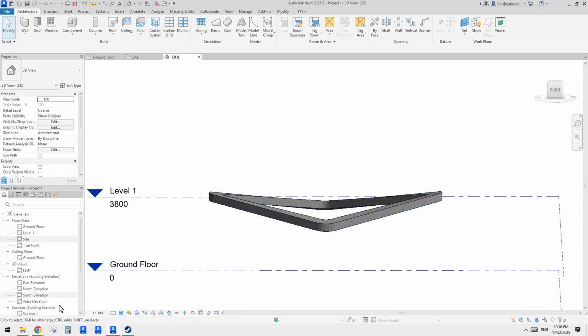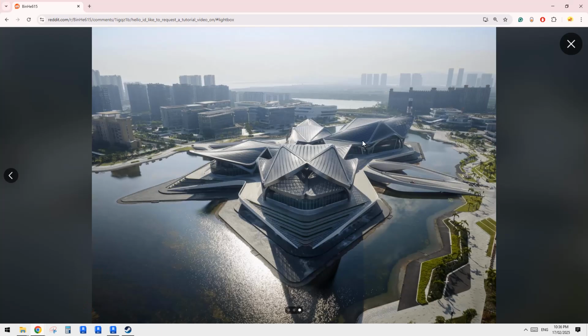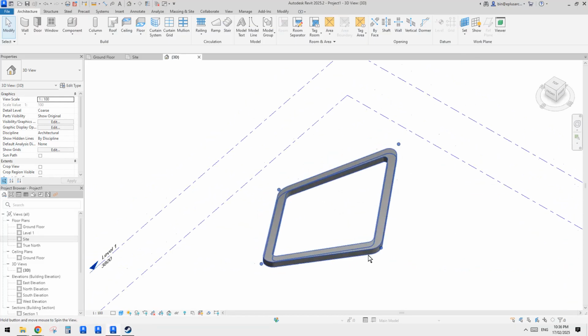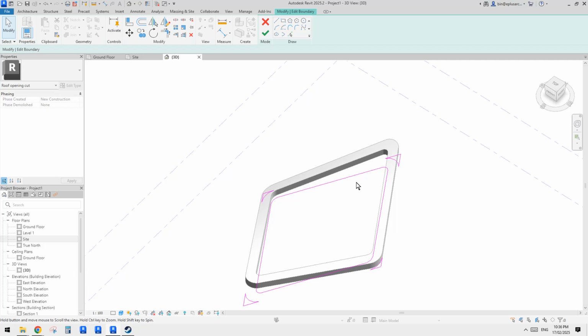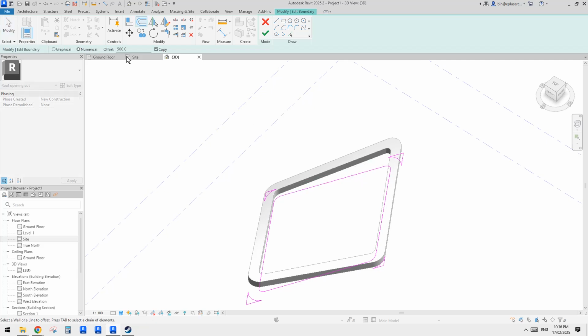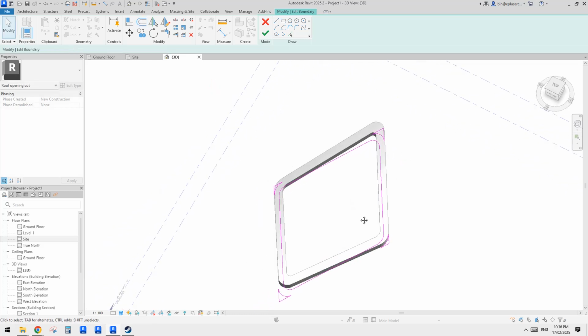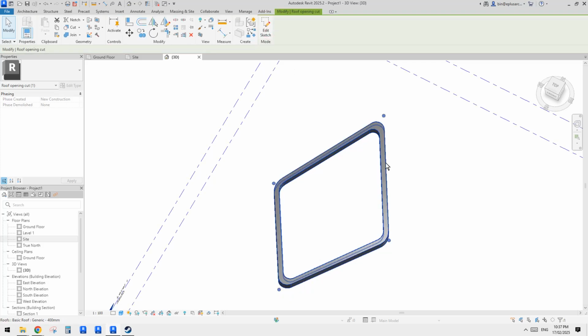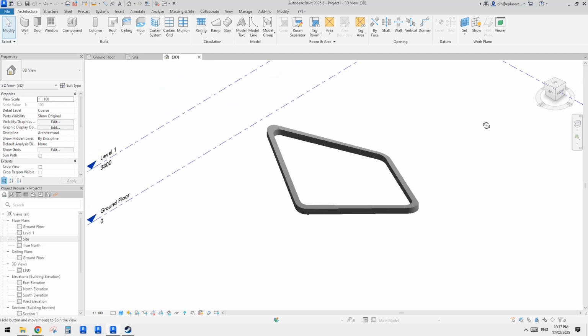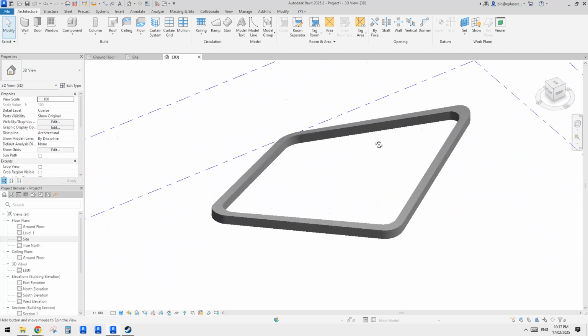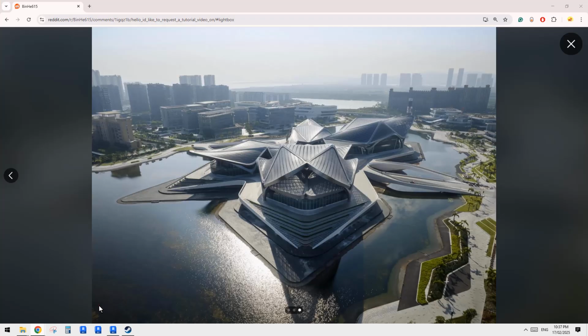Okay, and then quite similar to something we have here. And if you need to adjust the size, for example, we can use offset. So try offset. Maybe I'll just put in 200. Untick the copy and the tab. So this will offset all these sketches by 200. So make this 300 wide. So this will be 300 wide. Okay. So now we have this one.